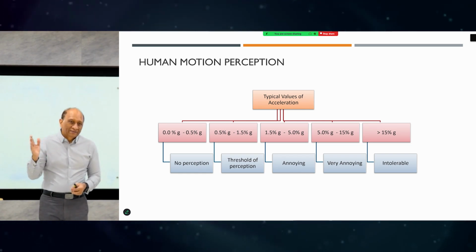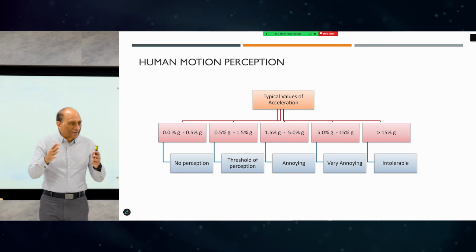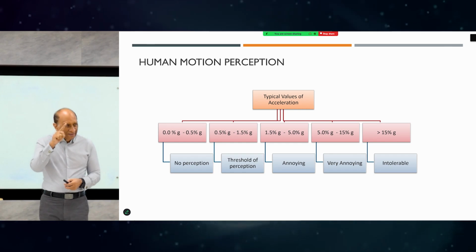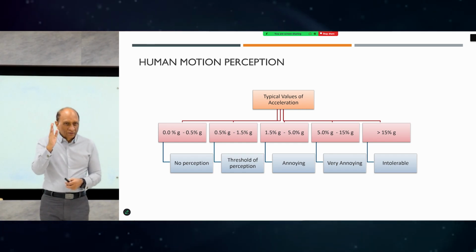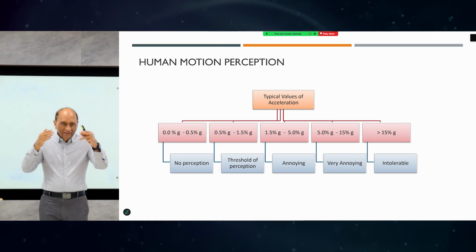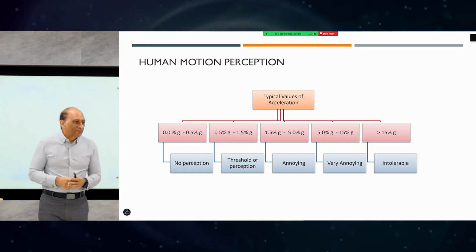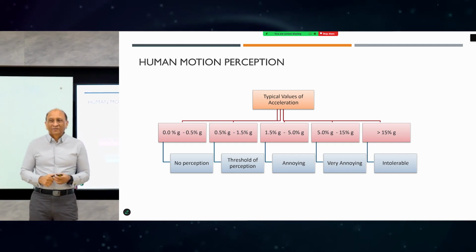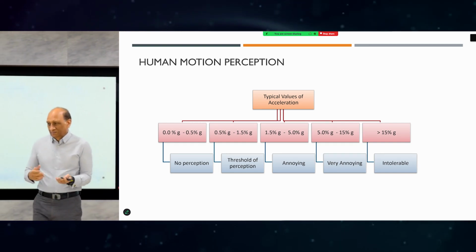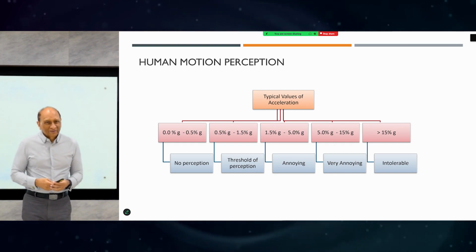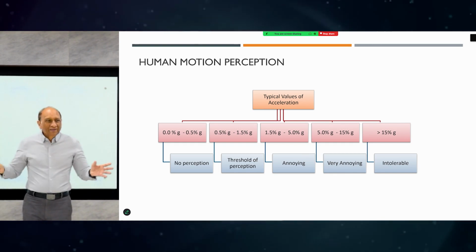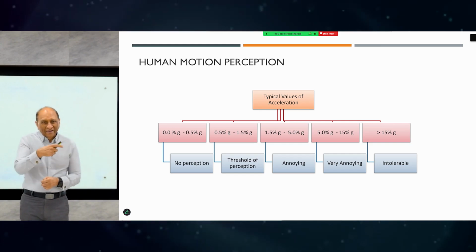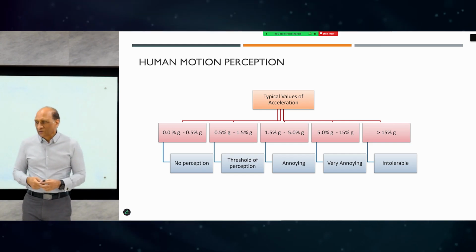Obviously in wind, even if they put in all the design and dampers and everything, it still has an acceleration which is slightly higher, and it creates noise at night because when it drifts, the windows creak and the walls creak. So people who have paid millions of dollars are always complaining to the owner that when I'm sleeping, the building is making noises, right? So the whole billion-dollar project, because of the acceleration and drift control, is now in trouble.